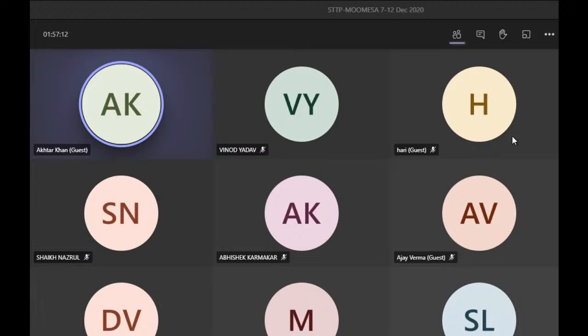So if you see, a total of 10 combinations will come. You can see the 10 combinations as per RSM given here: 1, 2, 3, 4, 5, 6, 7, 8, 9, 10. And all these 10 points can be located in a CCD design. This is how it happens, but it happens in the background. You will not come to know how it is happening, you will get only responses. I just wanted to explain how it can be represented mathematically.